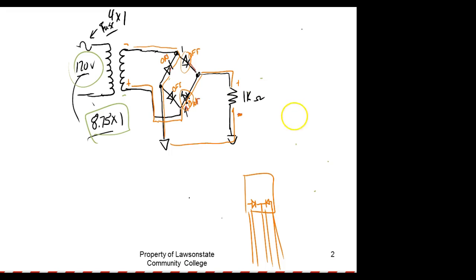Well, that would be a diode that I would use in a full wave center tap, right? But it's in one package. So instead of me having two diodes, this would be cheaper to buy, but it would cost more to repair. But when I'm engineering something and building them and selling them, I'm not selling them for the cost of repair. I'm selling them for the cost of selling, right? Y'all understand what we're saying?